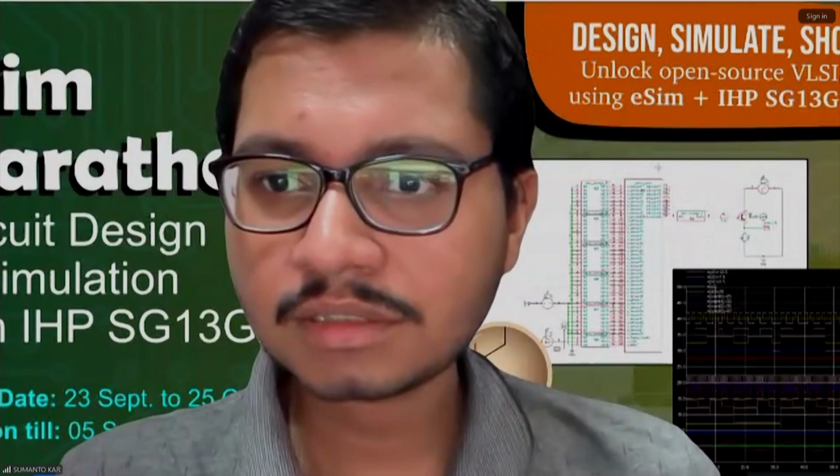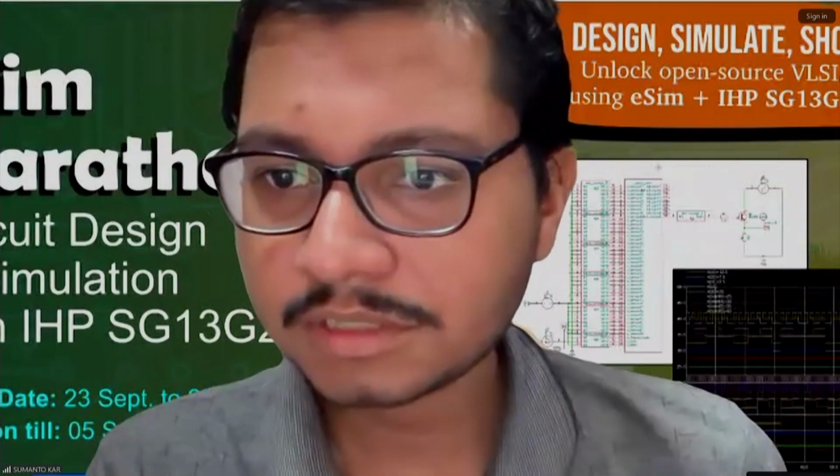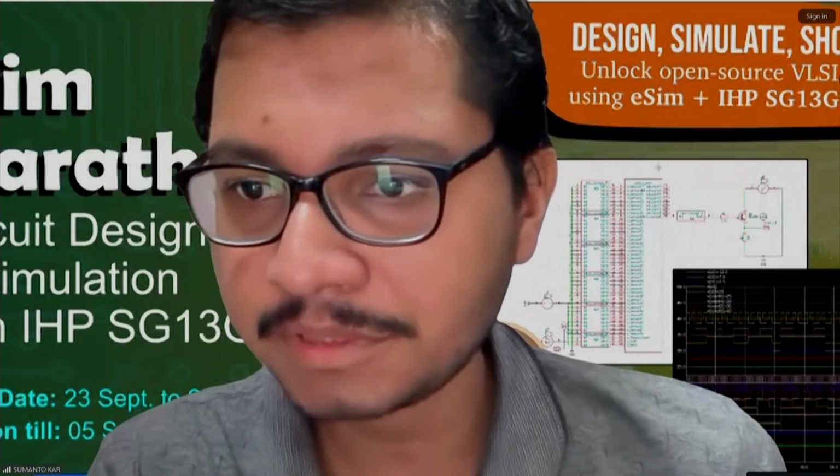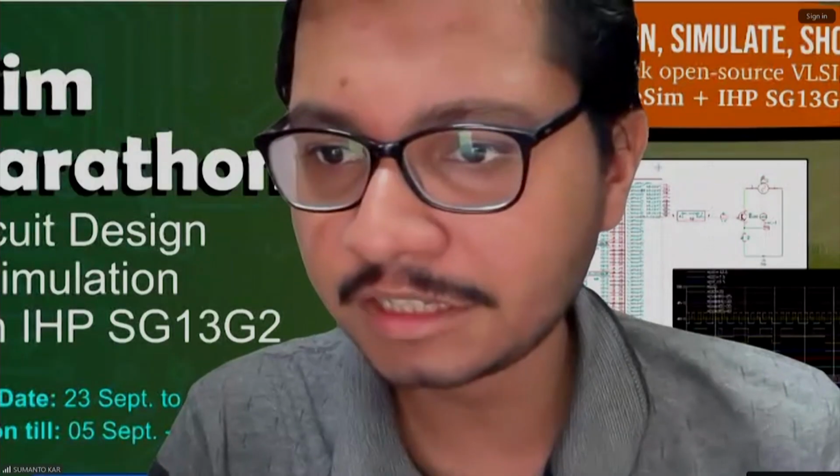Again, he's asking, Vipul is his name: does ngSpice support all RF analysis like SP, HB, PSS, etc. for the IHP PDK? We support basic DC, AC, and transient. There is an additional project to include harmonic balance, which is not supported by ngSpice.